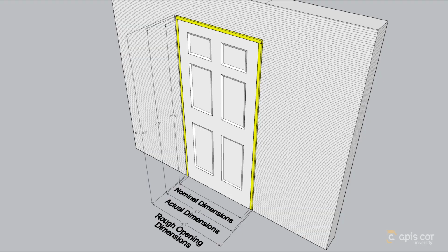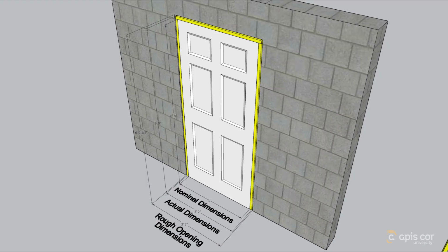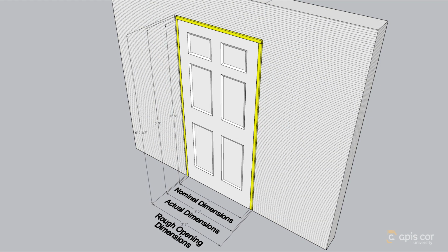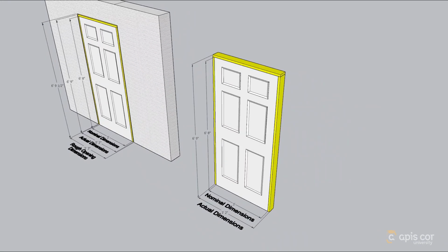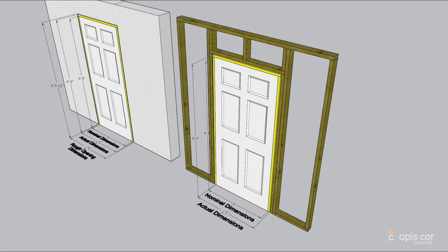If your door is designed to be installed into a CMU block wall, then the rough opening width in the product specifications is most likely the same rough opening width you will use for the 3D printed home's floor plan. However, some pre-hung doors are specifically designed to be installed inside of a wood-framed wall and not a CMU wall, which means they are designed to be attached to wood studs.